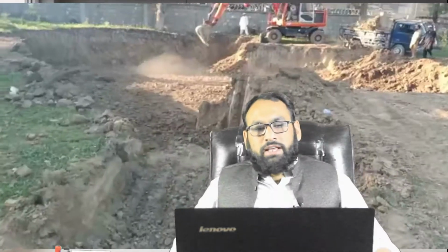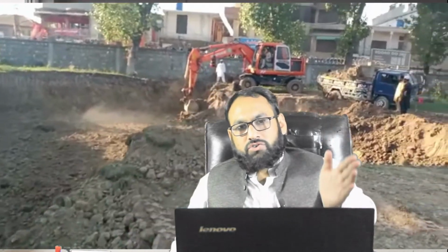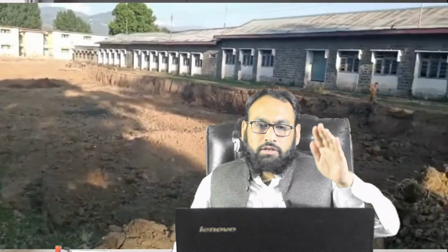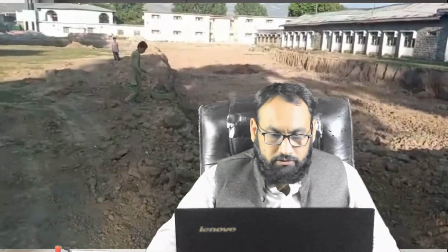In a video I will show you how we are excavating the earth for this particular project. You can watch this video for your information. The excavator is excavating the earth, and then he fills the truck for disposing of the soil outside, because this is not common material which can be used in backfilling. So we will use some other material for the backfilling purpose.